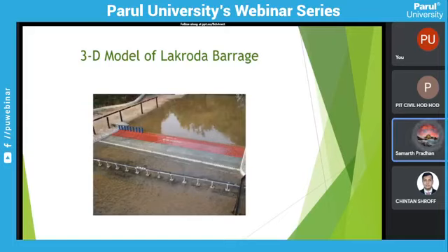Suppose you want to study whether the energy dissipating arrangement is proper or not. Out of this whole area, suppose there are 50 gates. Out of those 50 gates we select 2-3 gates which are crucial, and those are tested on the 2D model.